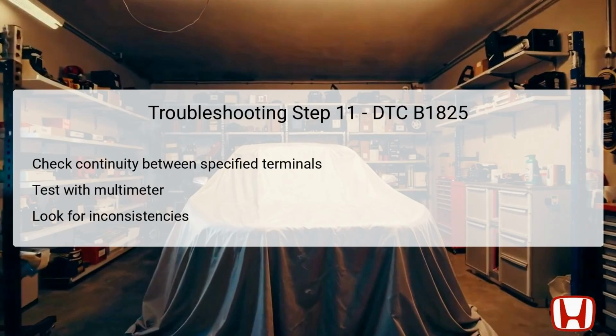If the multimeter indicates continuity, this suggests that the wiring and connectors are functioning as intended. Conversely, any inconsistencies or failures to indicate continuity may signal deteriorating wiring or defective components that need replacement. Proper verification ensures the integrity of the entire power seat adjustment system, validating that the slide pulse error issue has been comprehensively addressed and resolved.